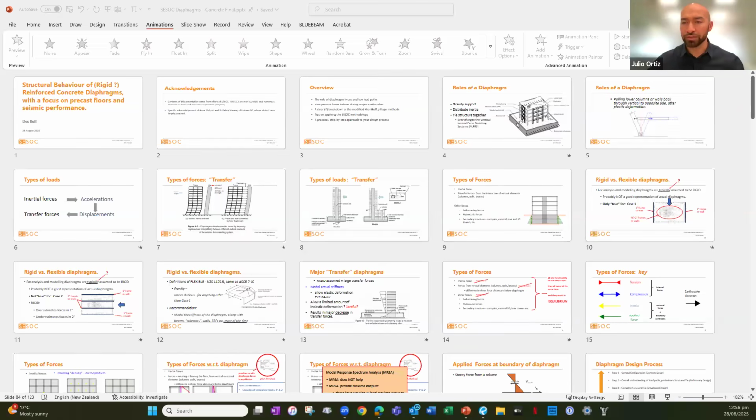Yeah, that makes sense. From Erickson and Sina: what reduction can be applied to diaphragm stiffness? Oh, the question just moved. Give me a second. There you go. What reduction can be applied to diaphragm stiffness to obtain the effective stiffness when modeling? Any recommendations to account for realistic diaphragms, including the topping, beams, and collectors? Especially for the topping or solid slab when used, and different stiffness of the elements when acting in compression and tension.